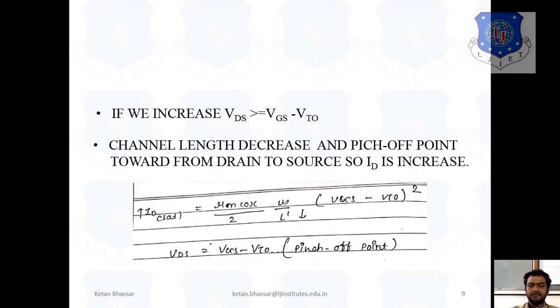So if we increase Vds to greater than or equal to Vgs minus Vto, the channel, which ran from y equal to 0 to y equal to L, now ends at L dash instead of L.